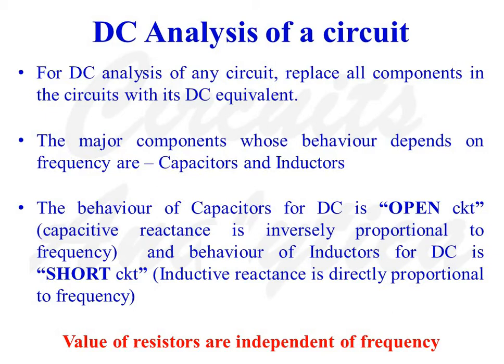The behavior of capacitors for DC signals is open circuit. Capacitive reactance is inversely proportional to frequency and frequency of DC signal is equal to 0. So for DC signals, capacitive reactance is equal to infinity or open. And inductors behave as short circuit for DC signals. Value of resistors are independent of frequency.